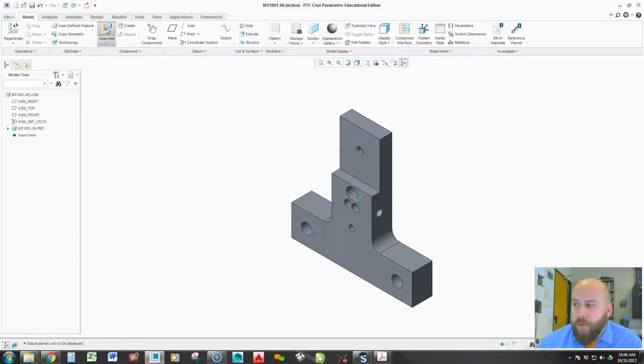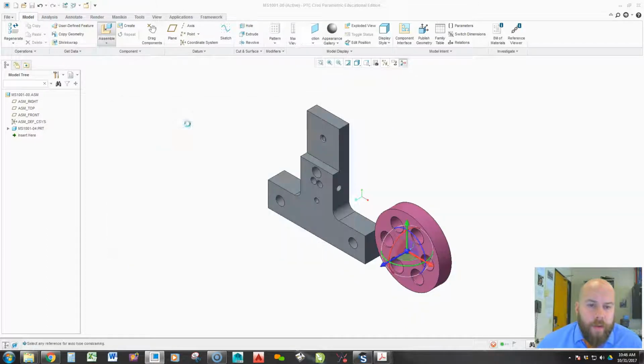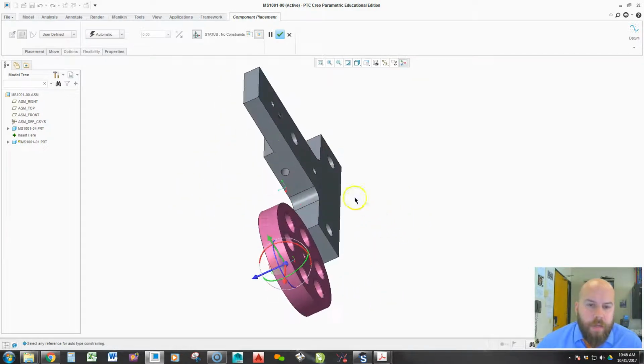So I'm going to say assemble. Okay, and what I'm going to assemble first is my wheel. Alright, now my wheel lines up with this hole right here. It has a pin that goes through it. Okay, and we're going to use that hole later to create a piece. But it also assembles to this side, a little space so that we don't have any sort of friction.